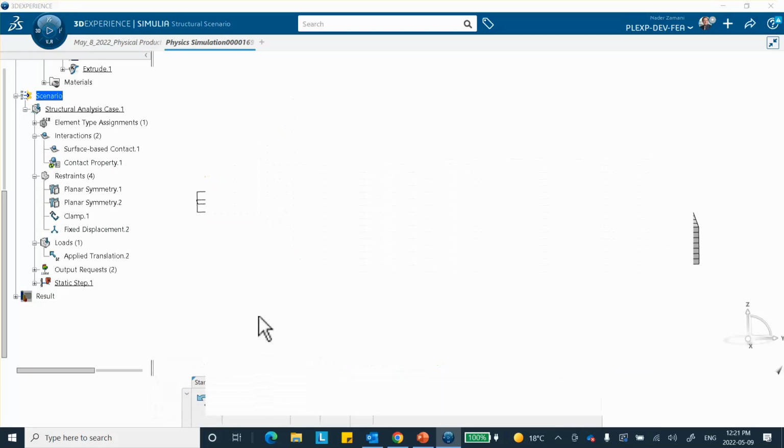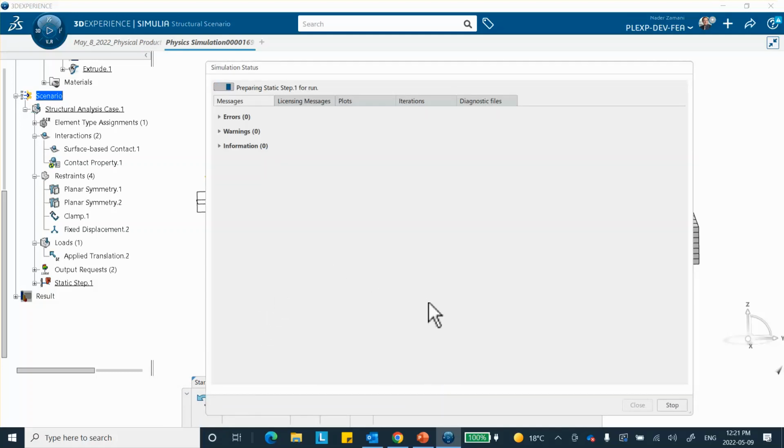And it just happens that in this particular problem, those two arrows are chasing away from each other. It just happens. But sometimes they may point towards each other, but still it penetrates. It has to do with whether the green and purple surfaces are mating, not necessarily with how those arrows are. Those arrows, one of them will allow you to flip the main surface's direction.